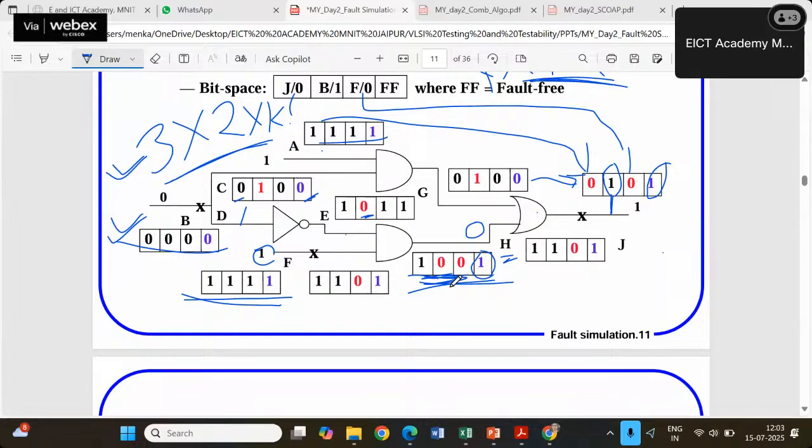We are talking about the difference between the parallel fault simulation and the deductive fault simulation technique. In the deductive fault simulation, we are going to deduce the list of fault values. In parallel fault simulation, we reserve, in this particular case, 4 bits all together to cover the set of faults. So every branch will have 4 bits reserved for it.